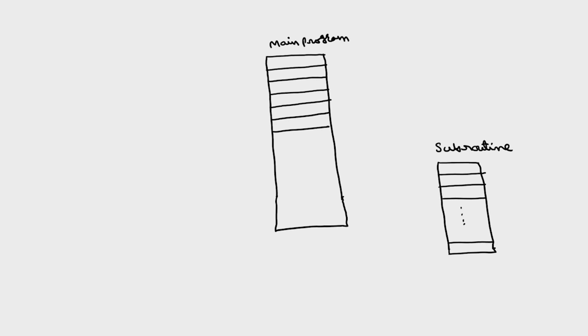This is the main program. If I want to call this subroutine, say call 5000 H. The main program will be in the code segment. If the code segment register contains the starting 16 bits of this address, something like 1000 H, this will hold the code segment. And this address is some 2000 H.